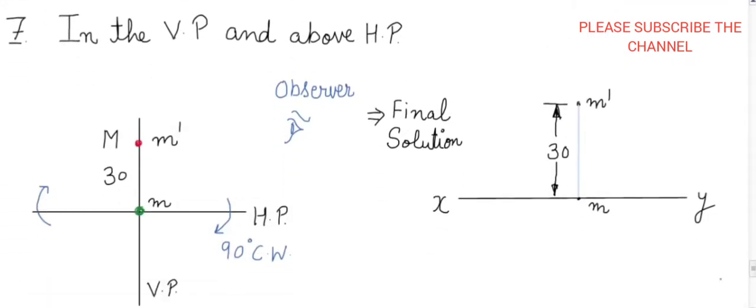So now move to the seventh case. The point is lying in the VP and above the HP. The point is lying in the VP and above the HP, somewhere like here. Okay, capital M shows the point's location, which is lying 30 mm above the HP but in the VP. The observer will see this point where the point is lying itself, which shows the front view of this point, small m dash. And when we see the top view from here, the point is lying on the origin. This shows the top view, small m.